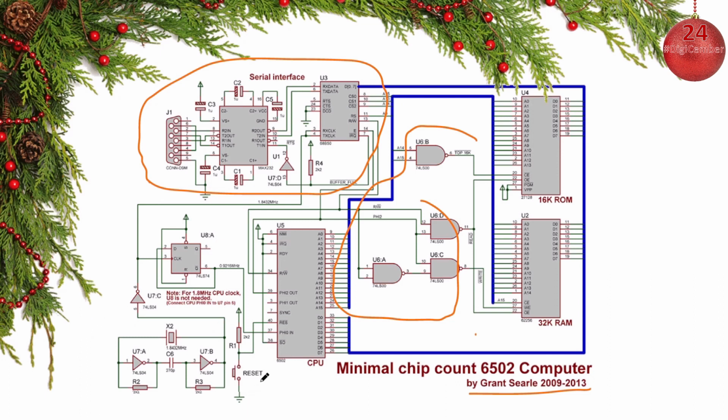Yeah, and he has also done just the hardware reset without any power on reset. You can see here, this has no capacitor here to actually make the chip reset when it's starting up. So this is not in the design of the 6502.